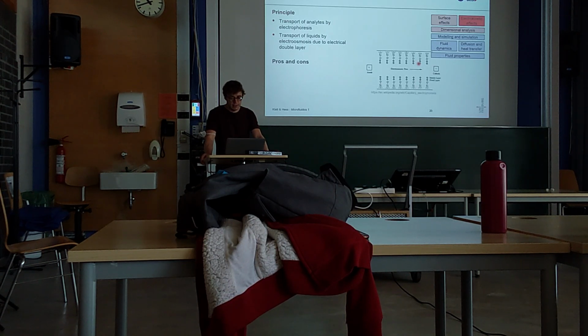If you think back to last week, what could be a big advantage of, in particular, electroosmosis? Think about a flow profile. You can transform like in a rectangular sort of. In a straight line, basically. Yeah. So you don't have this influence of the Taylor dispersion, which Nicholas presented, I guess. And so you can move all analytes at the same speed through your channel.